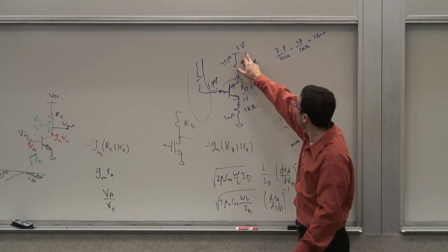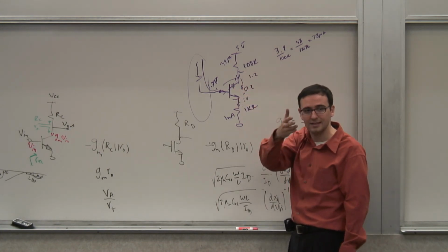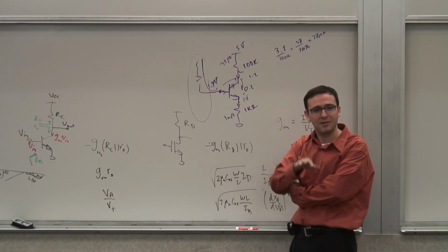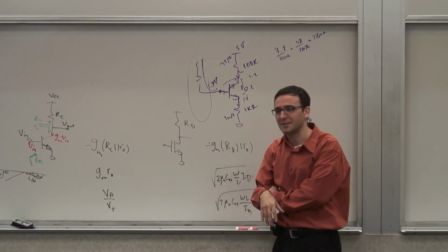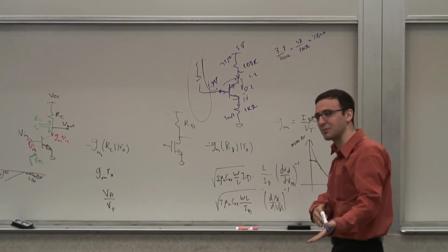No, this voltage and that resistor. And the current now, right? Exactly. So I was thinking, okay, I'm going to make this 1 milliamp. That's my favorite current because I know all the numbers for that. And of course, if I need something else, I can scale it from 1 milliamp. If I need 100 microamp, I can divide it by 10.